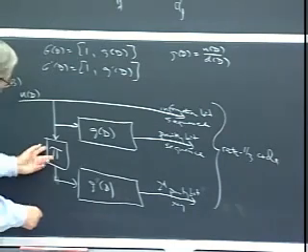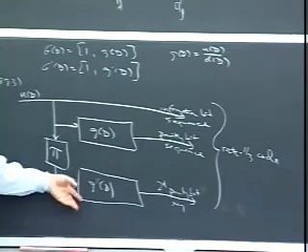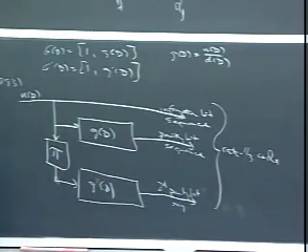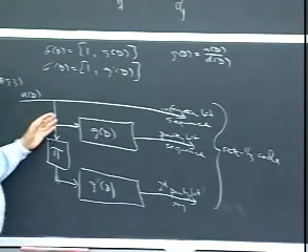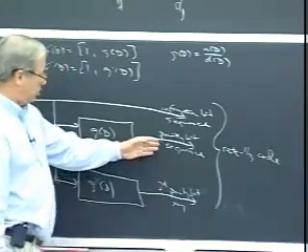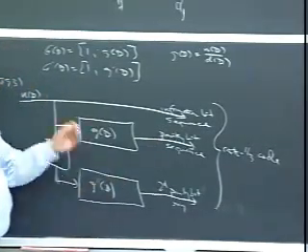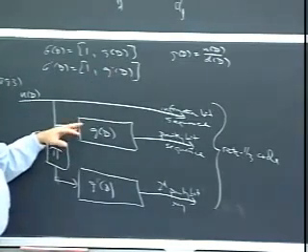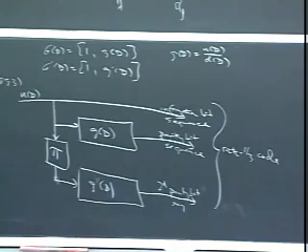And then when those 2 bits are permuted, they're going to come up in totally different places, so they're going to look like 2 individual information bits down here, and therefore they're going to ring for a very long time. The basic idea is you don't want an information sequence which gives you a short code word out of here and a short code word out of here. And making it recursive, having feedback, is what you need to do to prevent that. Also gives you better codes, but I don't think that's really why.